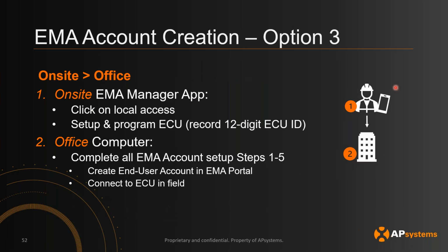And then the other option is to do everything on site first and then do off-site afterwards. So the way you would do it is that once you go on site, you set up the ECU, program and associate the inverters to the ECU. And then afterwards, you go back to the office and do the account creation. So to me, I personally prefer the third option. Our tech support agents prefer the first option.